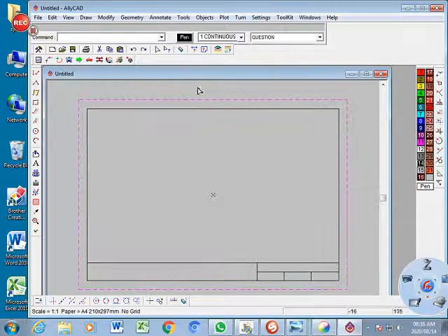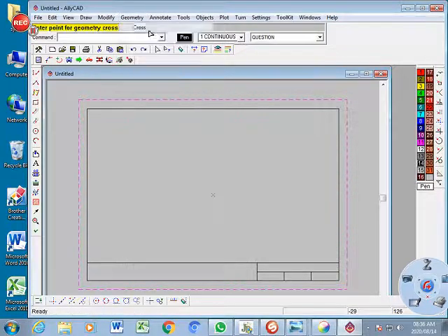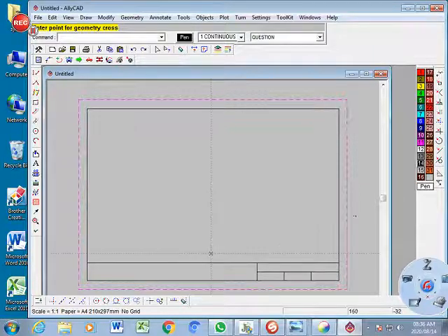So this is where I'm going to work. I'm going to start the geometry. I'm going to do a cross to create the starting point. So that's where I'm going to put my cross. I already have this straight line up, so I don't need this line, but I'm going to use my cross as my starting point. I like working with this snap cursor.